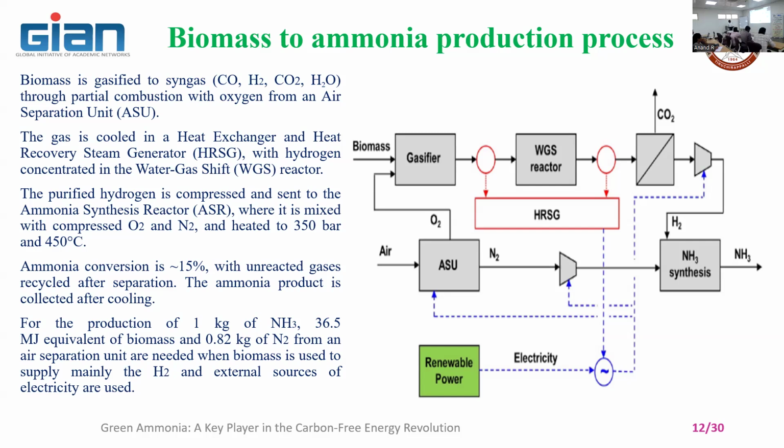From the gasification system, there are 4 different zones: drying, pyrolysis, oxidation, reduction. The zones may change for different designs. Ultimately, the gas comes out. If you take it from the bottom, it's called downdraft gasification. If you take the gas at the top, it's called updraft gasification. If we take the gas exactly at the center, maybe it's a cross-draft.